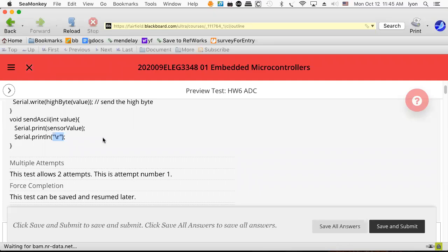If what you want to do, for example, the SIR1 robots use ASCII on an RS-232 line. They want a carriage return. They want that \R in there. And if you're on a computer that only outputs a line feed or outputs a line feed and a carriage return, then it's essentially confusing the microcontroller.